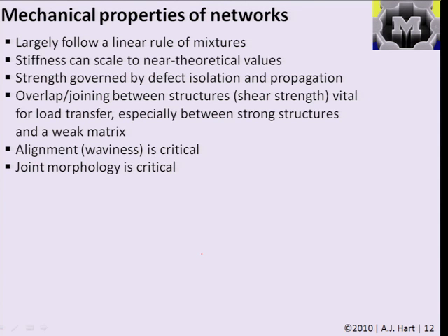But because in most cases, for example, adding nanotubes to a polymer, you have load sharing between the nanotubes and the surrounding matrix, you can get a significant enhancement before you have a continuous path. And in fact, it's the interactions between the structure and the matrix that are going to dominate often over the connections between the structures.